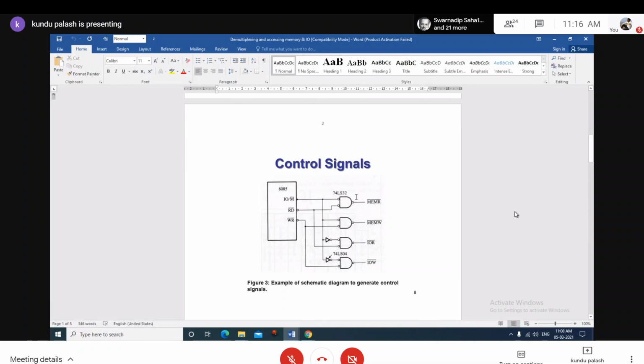Similarly, this is not unique, there may be a different combinational logic circuit according to the truth table. Now, what is the truth table? That means the information over these signals will be decoded or encoded, whatever it may be, at the output lines. So based on this, using the K-map, Karnaugh map method, we can find out what the actual logic gate circuit will be.